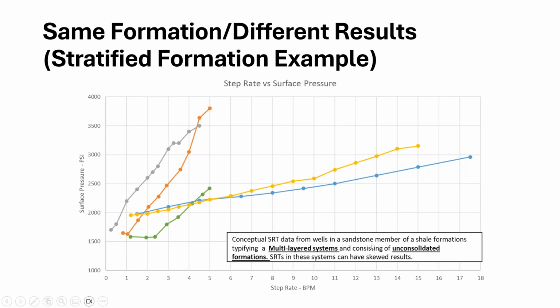So the step rate tests in this formation could be interpreted in different ways. You would have different results in a range of fracture parting pressures, and these may not actually be reflective of what is going on downhole.